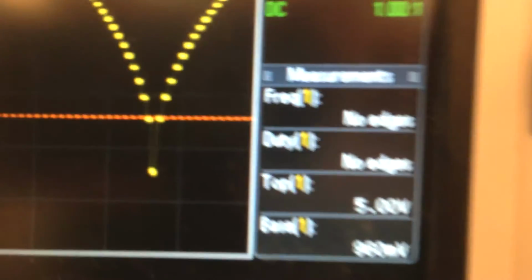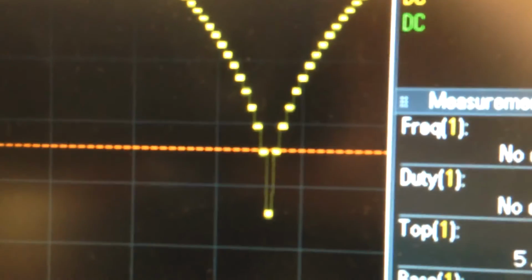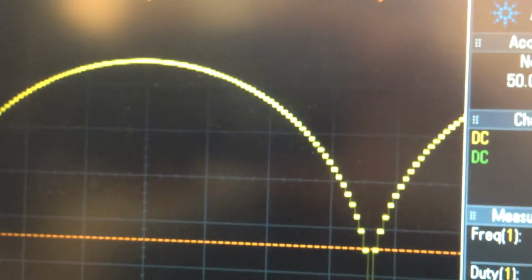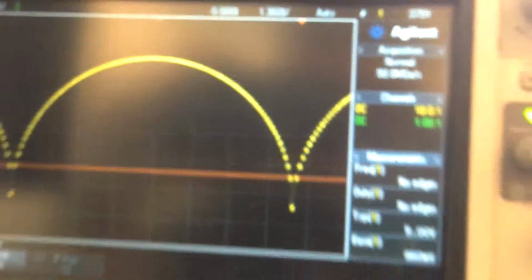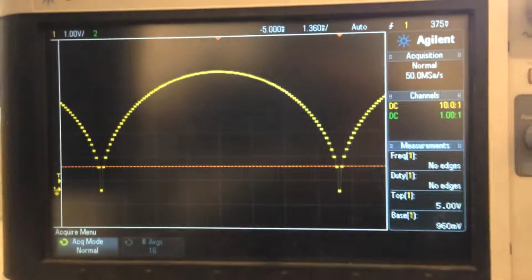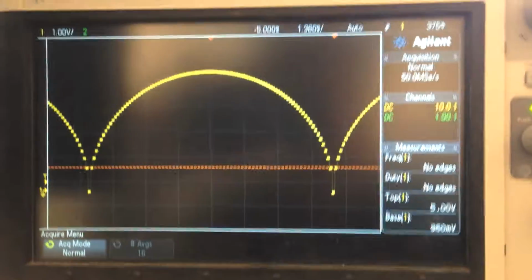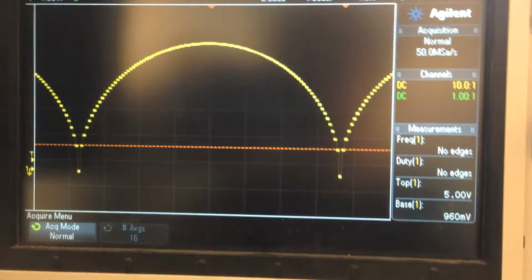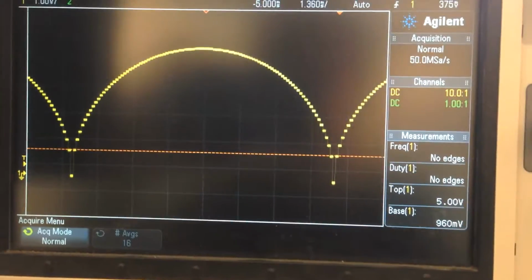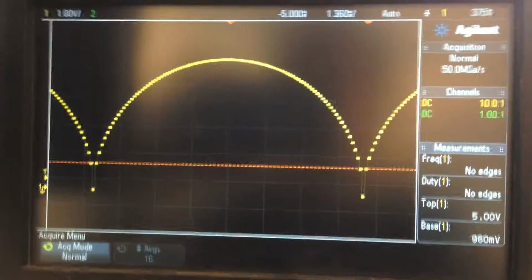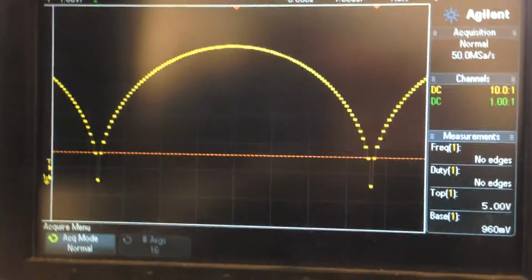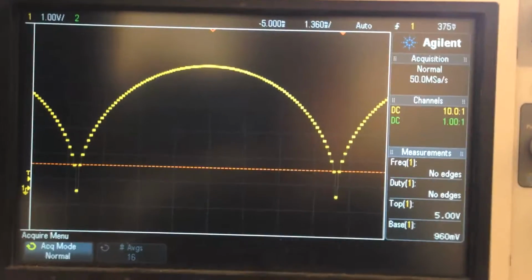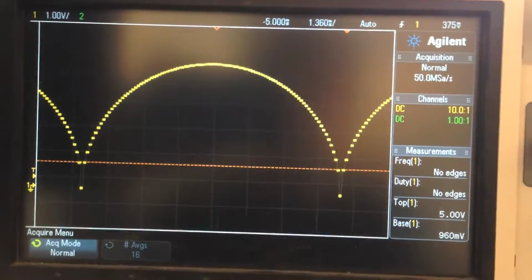And you'll notice that this is actually stepwise. It's not continuous. This is how the project works. It outputs one frequency for a certain amount of time. For a 100th of the period, it outputs that voltage level, and then outputs the next one the next 100th of a period. And so each wave you see has 100 distinct levels per period.